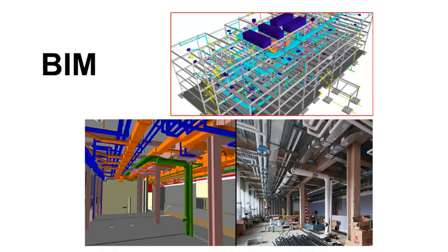Nowadays, if you modify a 2D drawing, you need to make sure all other related 2D drawings are also modified accordingly to maintain information consistency. This is not an easy task because it is a human task and the relationship of drawings can be quite complicated, especially in a large project. In the BIM approach, the information is managed in the 3D BIM model and all needed 2D drawings are automatically generated by the computer. Therefore, any modification in the BIM model can be easily updated to the related 2D drawings.